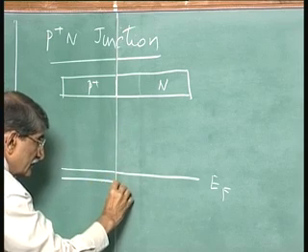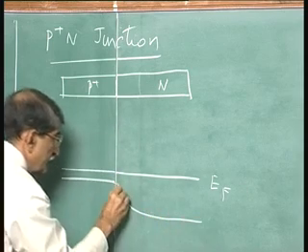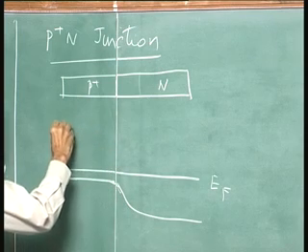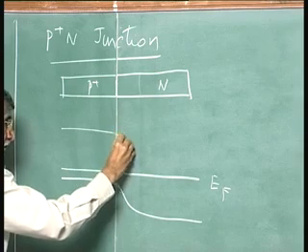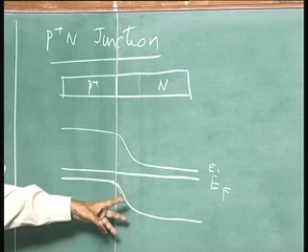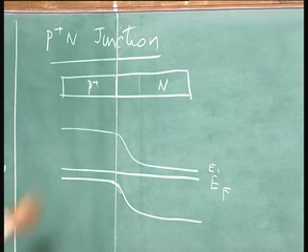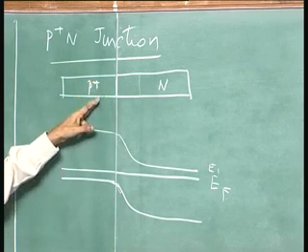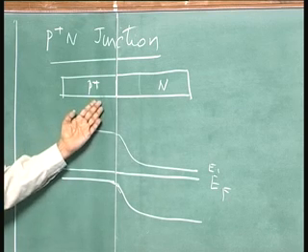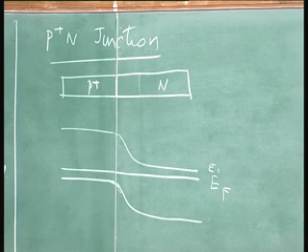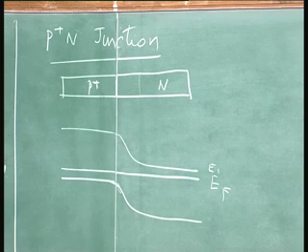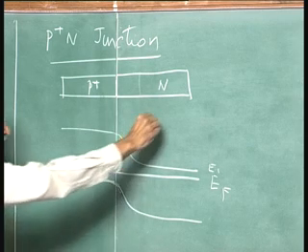From there onwards, due to the built-in potential, and here, that is easy. P type material, N type. I have not shown the Fermi level, not too much difference, but if that is P plus, it will be closer to that p-n junction. Or even if you do not put P plus, it is okay. Our discussion holds good for that. What will be the distribution here? Exactly the same diagram that we drew for the metal semiconductor junction you can put. It goes like that.